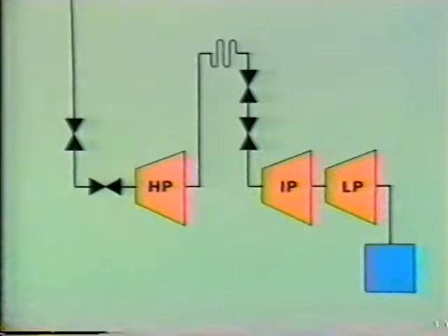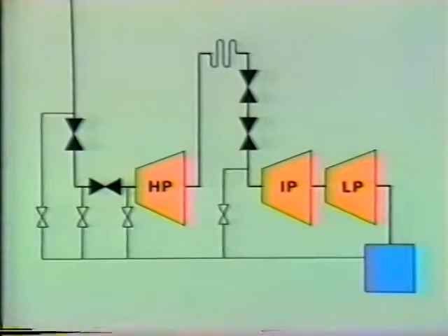However, turbines are equipped with valves that get rid of these droplets before they can strike the blades. These are called startup drain valves. In this block diagram, the startup drain valves are located at points in the steam path where moisture is likely to collect. Generally, the moisture that's collected is routed to the condenser. These drain valves are opened before starting the turbine and are usually not closed until the turbine is carrying load, when enough time has elapsed so that there's no moisture left in the steam or turbine pipes.